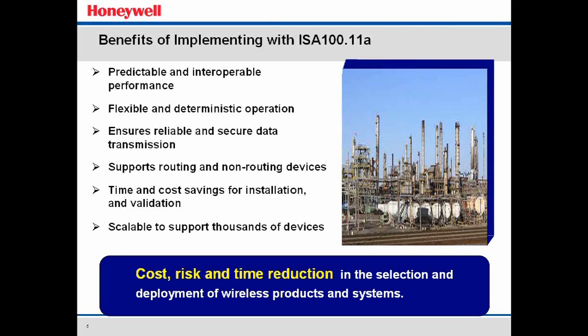What that gives us is the flexibility to solve problems. If you have an outlying transmitter, for example, that can't see back into the network, to the mesh, then you turn on transmitters that are closer to that problem transmitter, and now it has a way back in. We didn't need to extend the network to catch one transmitter. We have ways to overcome those problems like that. But at the beginning, on the front end of the project, I don't want to have device routing in mind. I want to build it out properly in the first place.